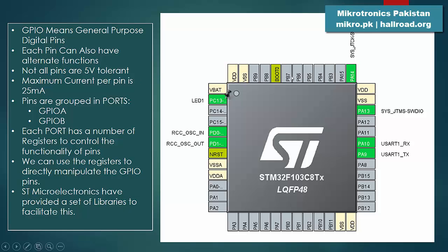And all these pins are not 5 volt tolerant, almost. We should assume this because this is a 3.3 volt microcontroller. So the maximum input voltage coming as a signal to these pins should not be 5 volts, it should be 3.3 volts. If you are giving it a signal from another microcontroller like Arduino or something else which has an output of 5 volts, make sure the pin you are connecting to can tolerate this 5 volt signal or not. In any case, more than 5 volts is not tolerated at any level.